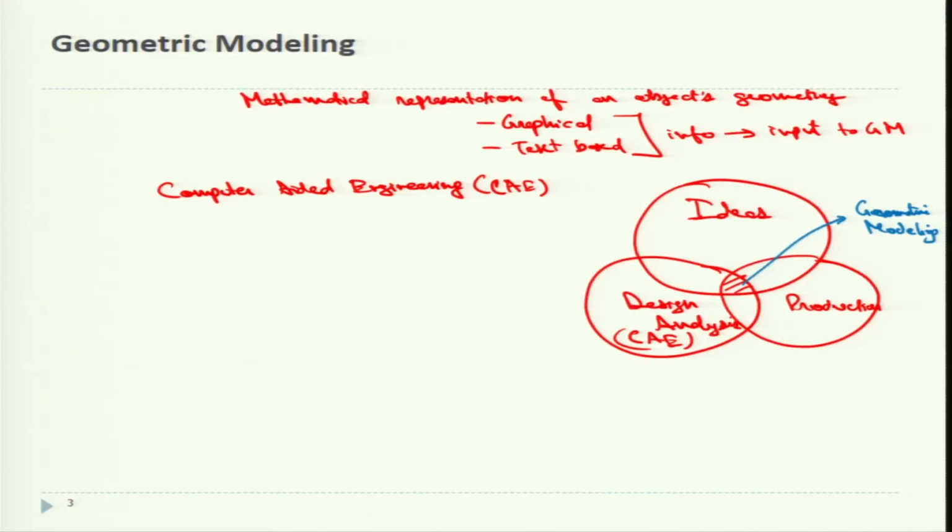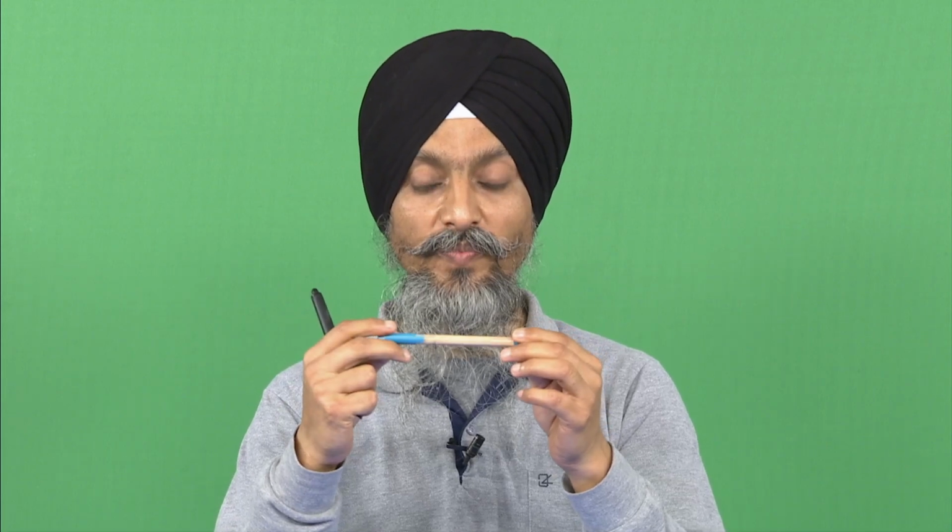For instance, this is a model of a pen. In the pen, this is the fit. If I click it, there is a sound fit. This is known as a push fit. It has to be a push fit. That means the tolerance, the dimension given to this projection and this serration given here, has to be overlapping. That means interference has to be there.